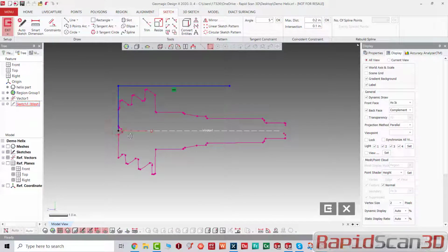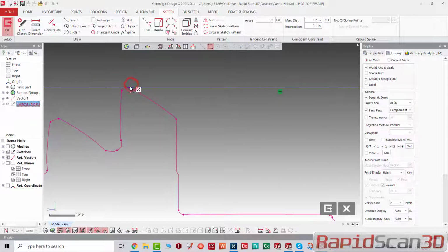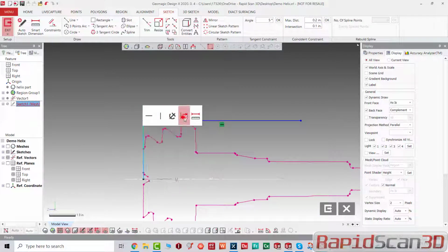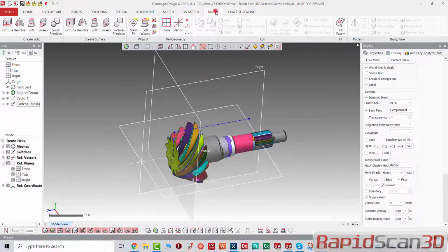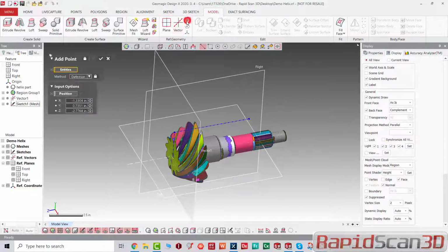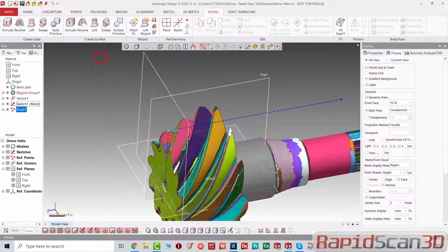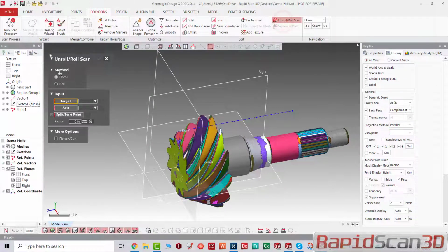The purpose of this practice is that we're going to understand how to unroll and roll the mesh accurately from the points and axes and vectors. So we're going to convert them into construction lines. Now I have a start and stop point, which means my mesh can only be unfolded and folded at this exact point. And if I don't do it right, then my mesh will not be wrapped correctly and my 3D curves will not be accurately projected on the surface.